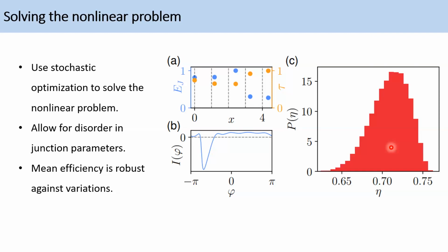Follow-up question. The junctions that we observe, the normal tunnel junctions, always intrinsically have higher harmonics already, like 3%, for instance. How would that affect your analysis? I know that in principle you can take care of it by engineering, but if you require 2% in EJ and you get like 3% of 2% EJ2, EJ3, and so on, what's the idea behind it?